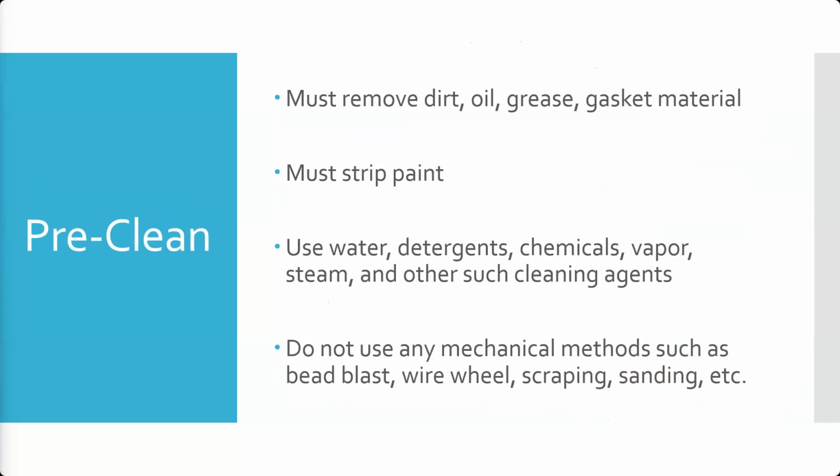Steam, high temperature water. That's what we'd use in the factory environment. We'd use something called a hot seat, which is basically a high pressure washer that puts out water at about 200 degrees Fahrenheit. It's used to strip oil and grease without using any kind of chemicals.